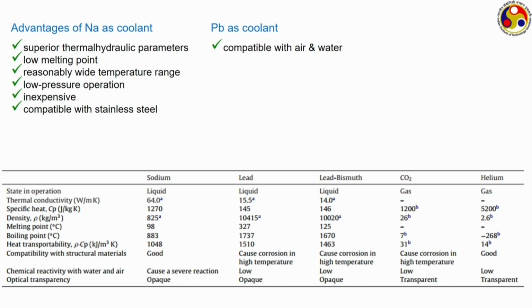It is very compatible with both air and water, and therefore, in case of LFRs we do not need to have that secondary loop or intermediate heat exchanger loop. In case of SFR, we need that intermediate heat exchanger, because the primary coolant, which is liquid sodium, should not come in contact with the water which is flowing in the external circuit.